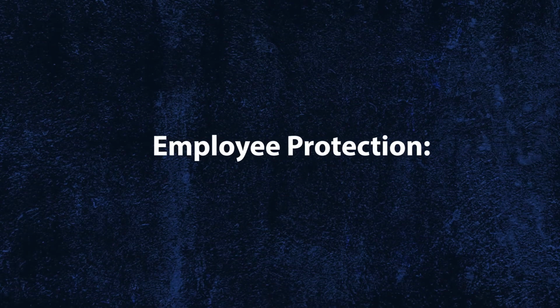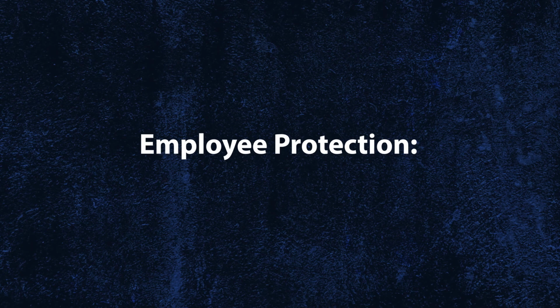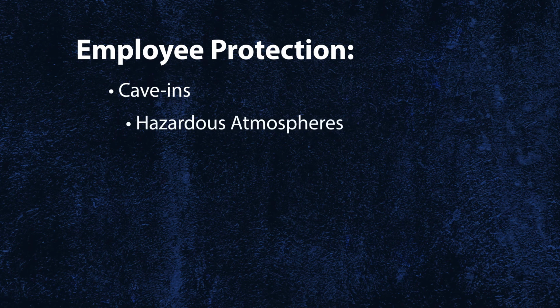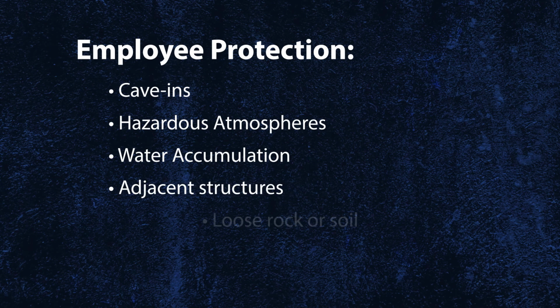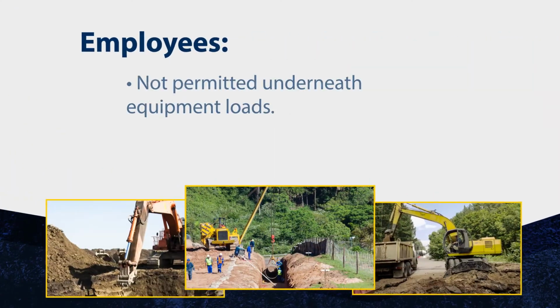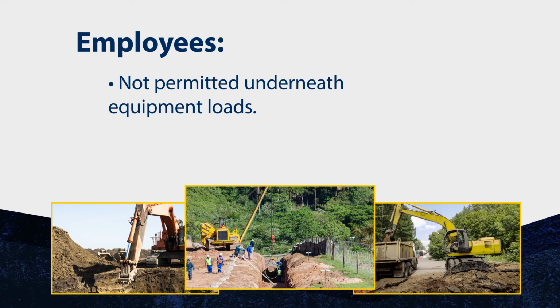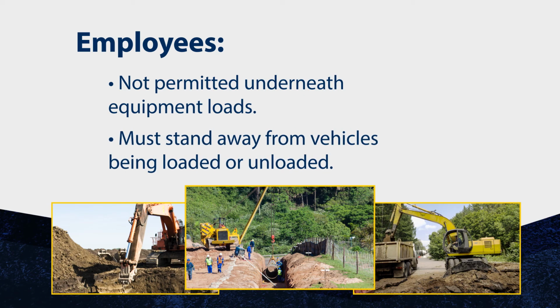Finally, you must protect your fellow employees from all possible hazards that can happen during excavations, including cave-ins, hazardous atmospheres, water accumulation, adjacent structures, loose rock or soil, and fall hazards. Employees are not permitted underneath loads handled by lifting or digging equipment and must stand away from any vehicle being loaded or unloaded to avoid being struck by any spillage or falling materials.